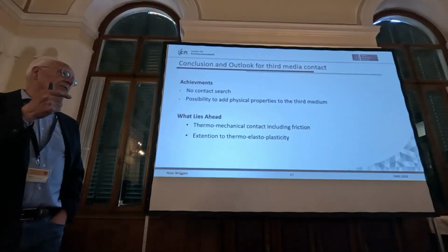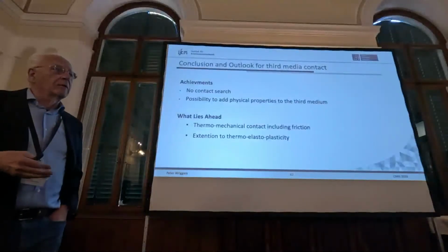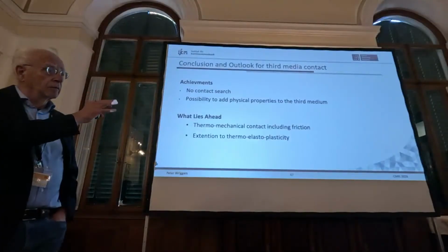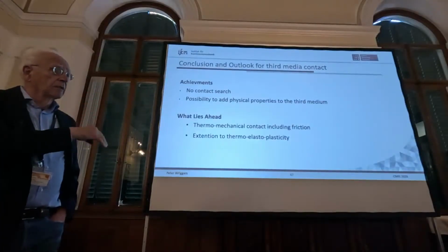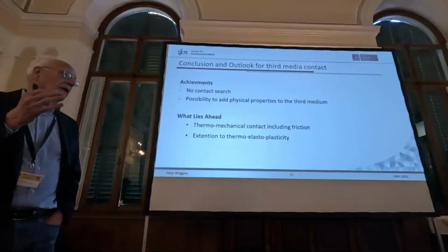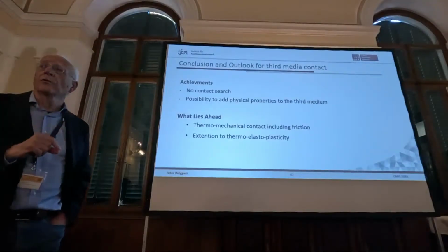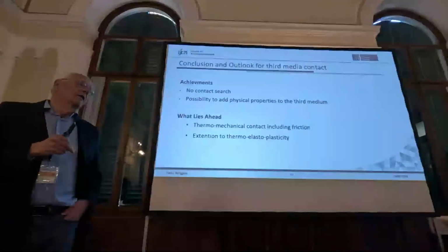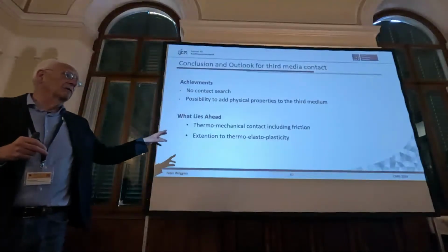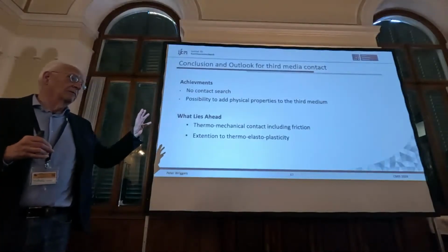So basically, we have some experience with gamma. You can link it to the bulk modulus of your solid, and take it 10 to the minus 6 or 7 times smaller than the bulk modulus in the solid. That works. And in our papers, we have set up some ideas on how to choose the regularization parameter.